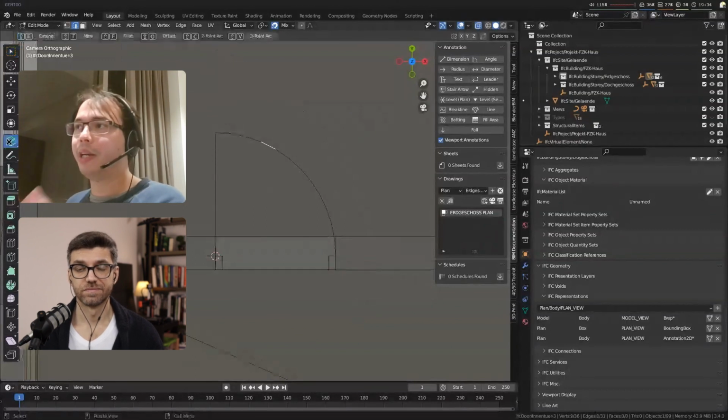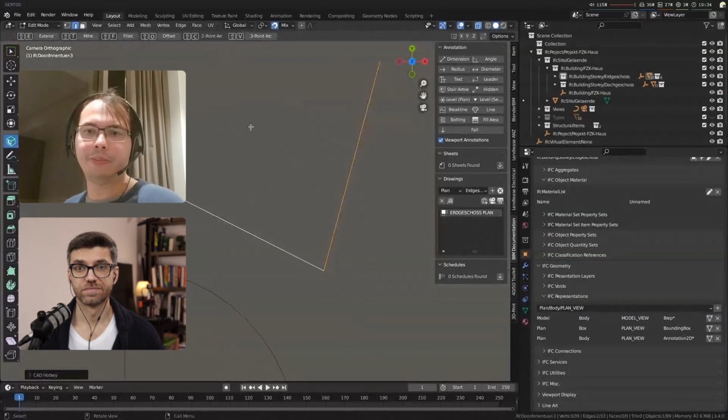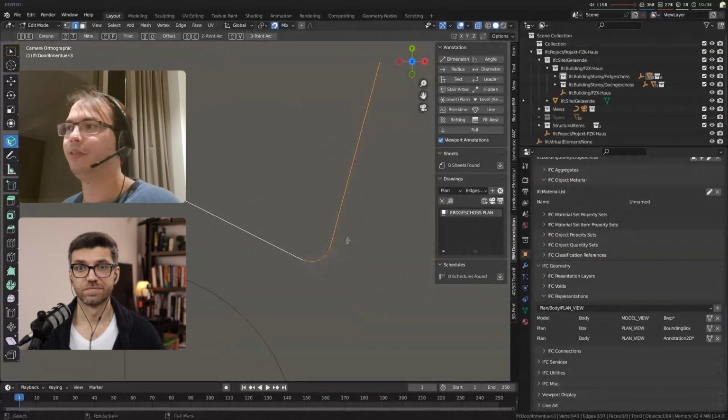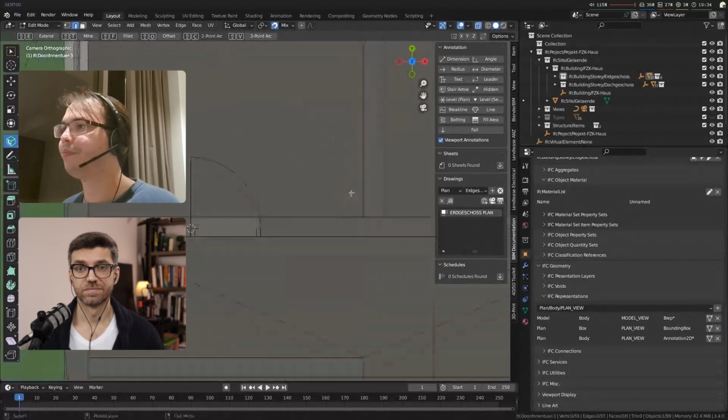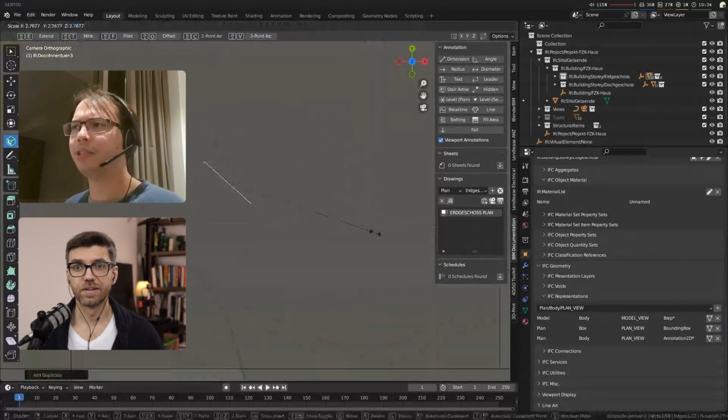So great. And by the way, BlenderBIM does add a series of CAD functions. So for example, if I had two lines that I want to extend or trim, all those types of things that you might expect, or draw a 3-point arc or fillet things and so on, it's all in there. Do you have an offset tool? Yeah, of course. That's a really useful one, isn't it?